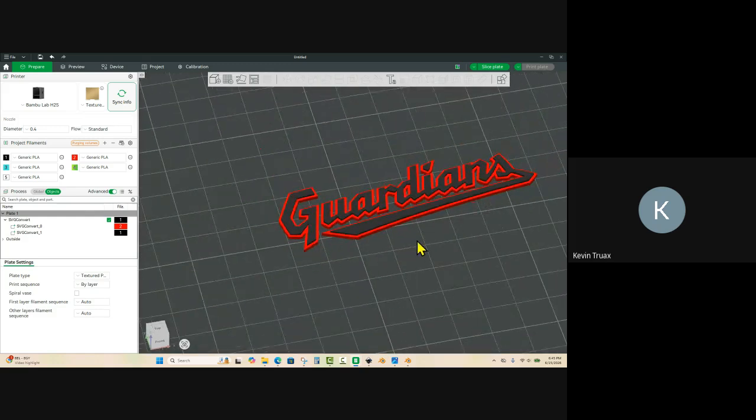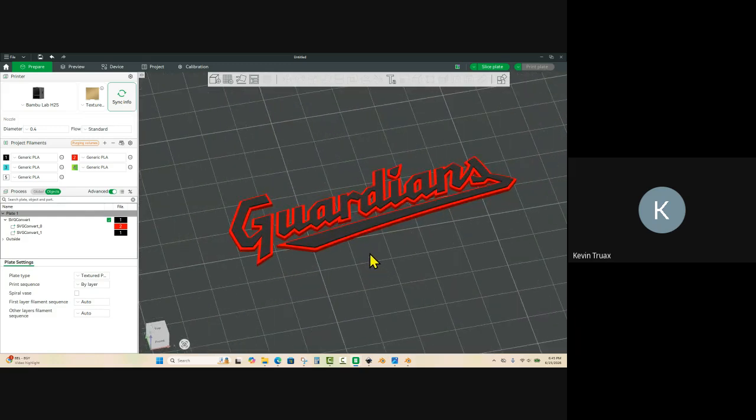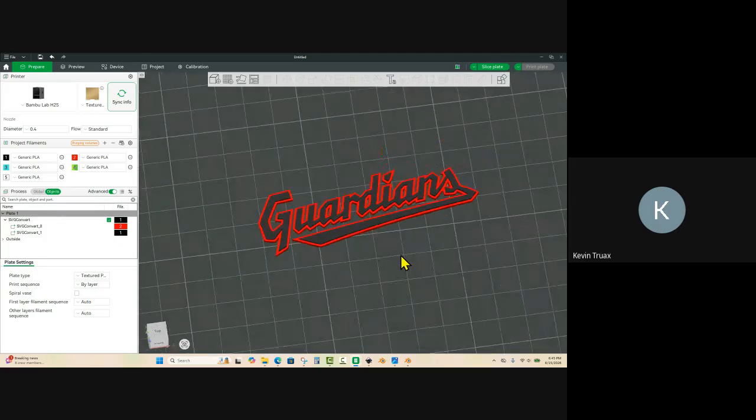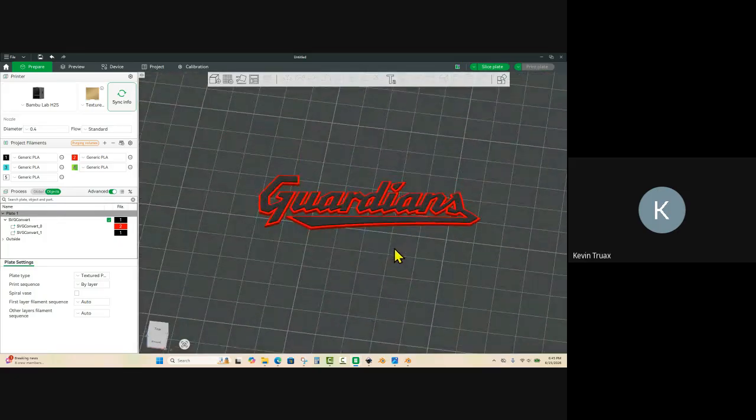And that's the way I always set up my cap files. Now, if this was 3 colors, the third color would be at 1.5. So I always add a 0.5 millimeter for every color. Each individual piece is only 1 millimeter thick, but we add to the Z just a 0.5 millimeter. So there you go. So this is ready to go for a cap.